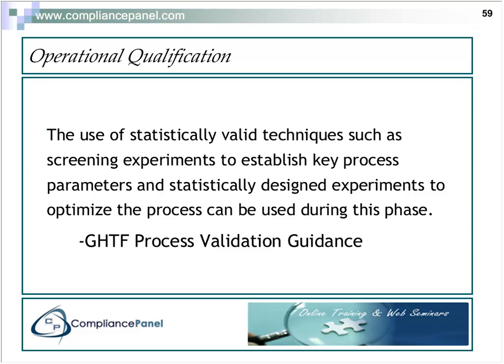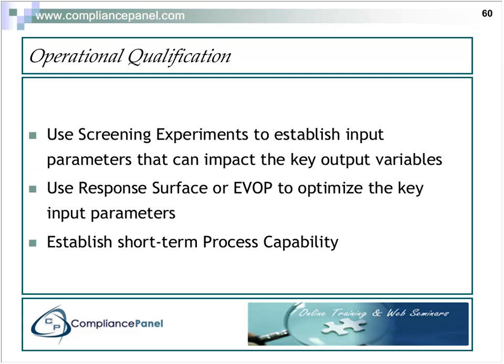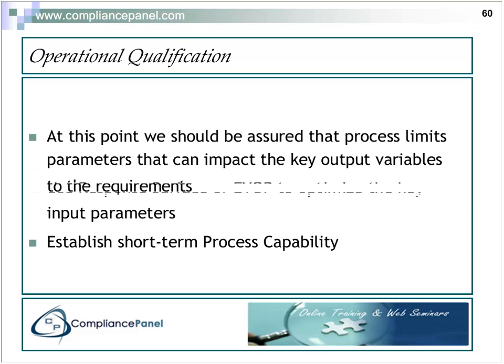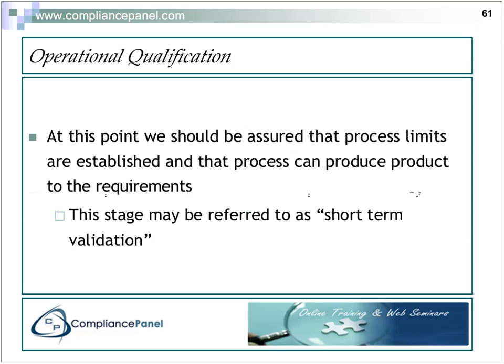Statistically valid techniques can be used during this phase. And again, this is a quote out of the GHTF process validation guidance. Okay, we're going to use screening experiments as I described earlier, response surface as I described earlier to optimize, and we're going to establish short-term process capability. And so now we know the process can produce product to the requirements. So we have completed our short-term validation.